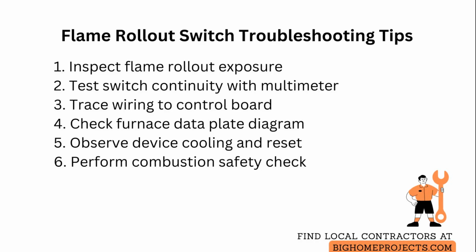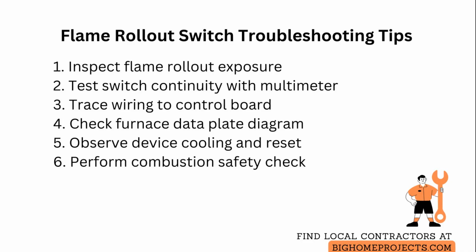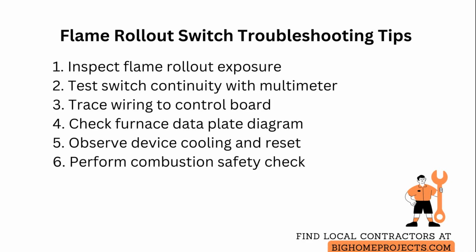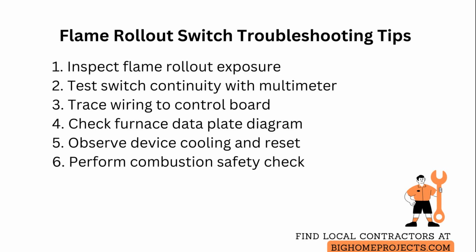To diagnose at home, turn off power, inspect the switch for obvious discoloration or melted housing, and test it with a multimeter for continuity at room temperature. Then restore power and observe whether the device cools and the circuit resets.